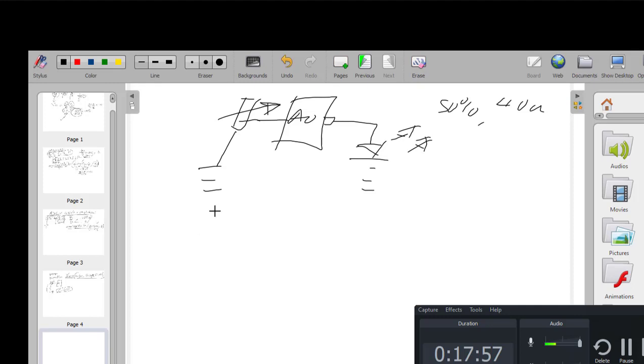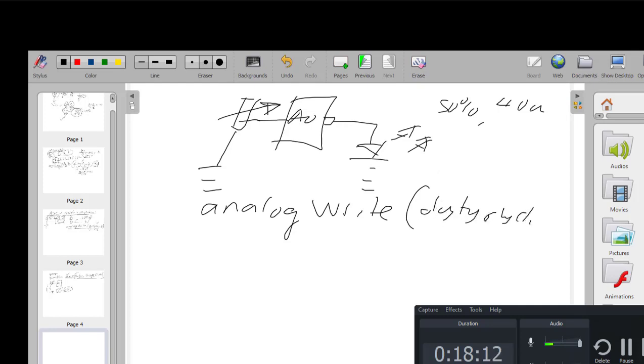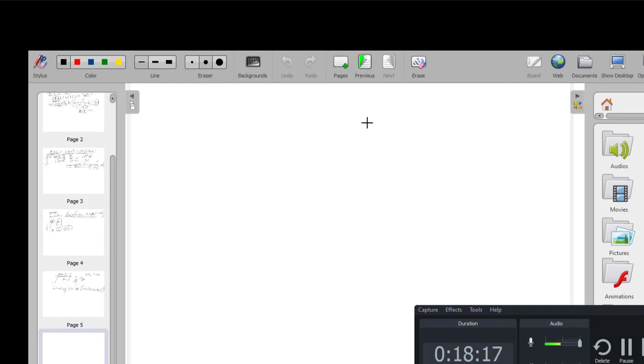And then we're going to use the analogWrite command. The analogWrite command will get whatever we have read from A0, but then mapped between 0 and 255, and then we're going to output that to pin 3. So now, real quickly, let me just show you how we can approach the coding. This is what we're going to do in approaching the coding.